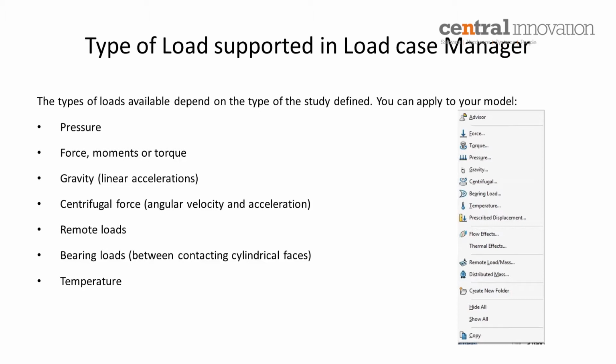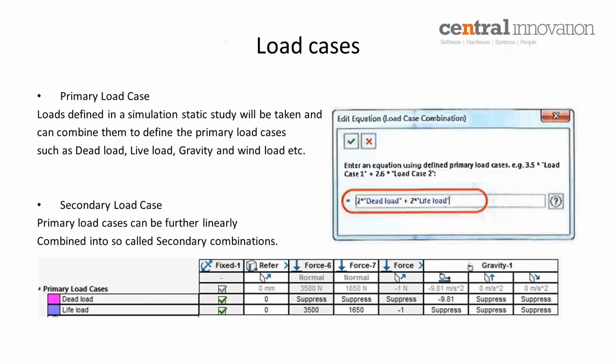Not only the loads. If you want to define a predefined displacement, for example, I can use reference geometry, set the displacement, and limit the displacement in a direction. I can manage the displacement value inside the load case manager also. I can manage the fixture definitions. I can give different fixture definitions and test my design. Okay. And this is an example.